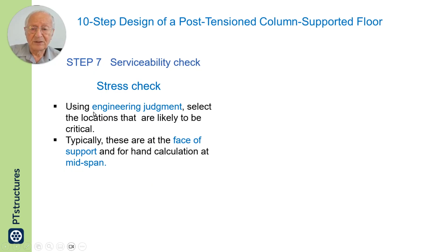Now, using engineering judgment, we select the location where stress check should be carried out. In hand calculation, typically face of support and midspan is used.